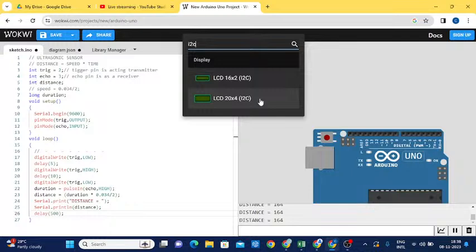Okay, I2C LCD, I2C is nothing but a type of protocol. Using this protocol, it is a two-wire communication. Two-wire communication means we need not use a lot of wires. If you are using the normal LCD, we have to use maximum 4 or 5, nearly up to 6 or 7 wires.